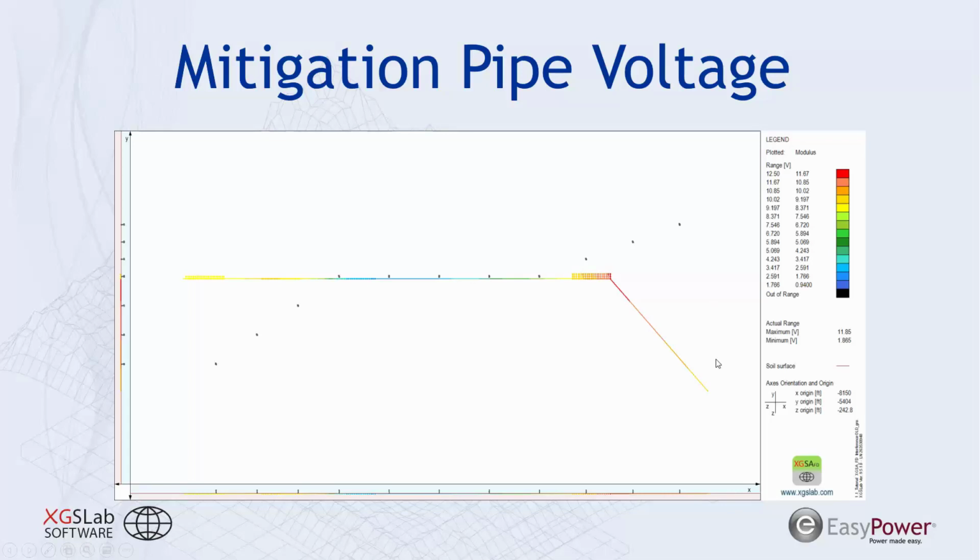And one thing to note too, when you're making these sorts of connections, you may not be able to directly connect any sort of grounding to the pipeline. You may need to consider existing cathodic protection, or that whatever you're introducing can cause new corrosion issues for the pipeline. So maybe you need to use steel rods instead of using a copper plated rod for your grounding.